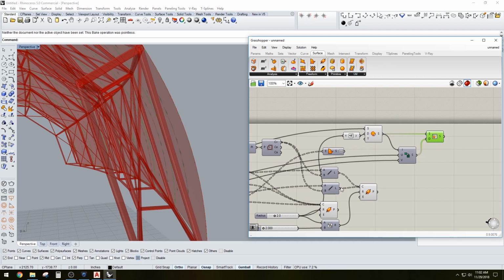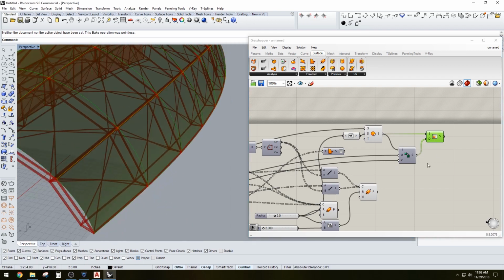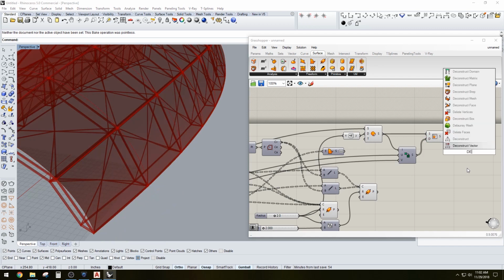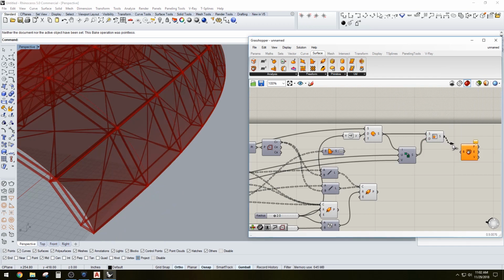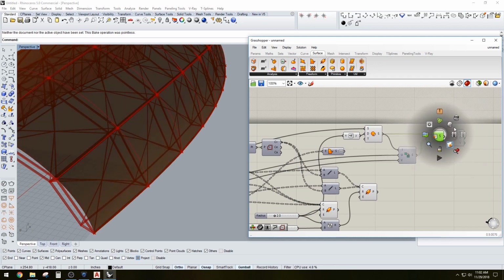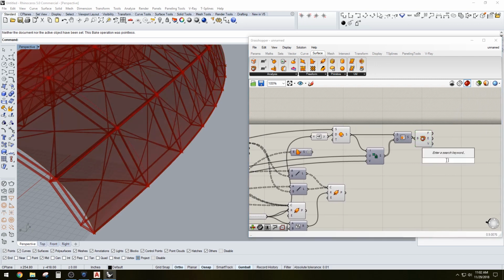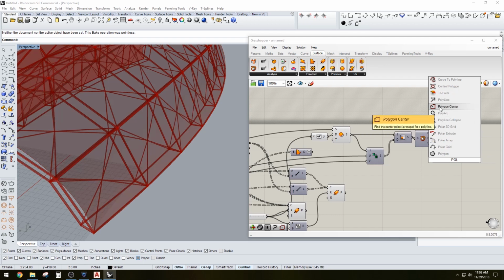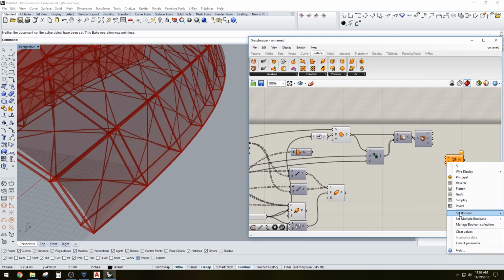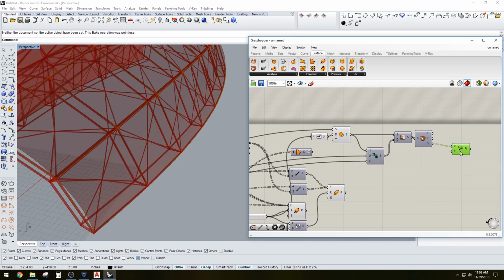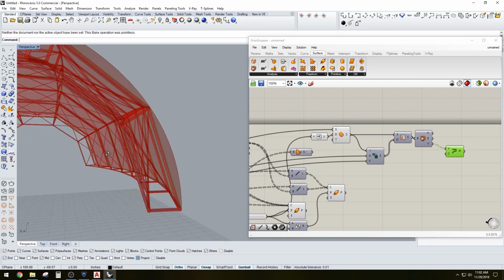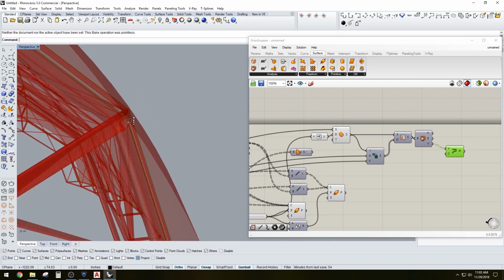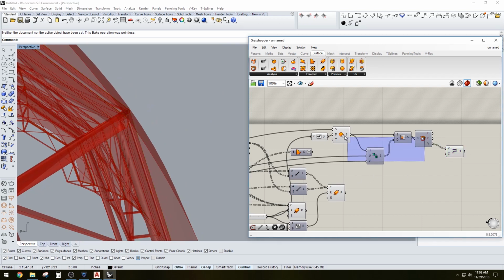So to make sure that we're doing it right on top, we're gonna deconstruct the B-rep, which is gonna give us, once again, a bunch of vertices, a bunch of faces, and a bunch of edges. So we're gonna create a polyline. So let's hide this again. We're gonna create a polyline that's closed, so I'm putting it to true here. It's a little bit off screen there, but once we plug in these curves, we have that rectangle sitting right on top of that pipe, which is exactly what we wanted.